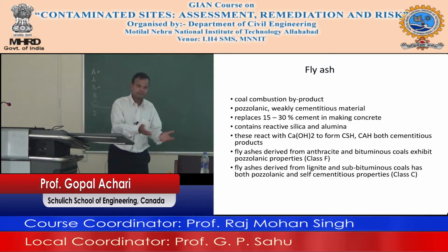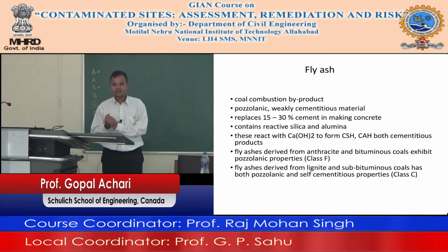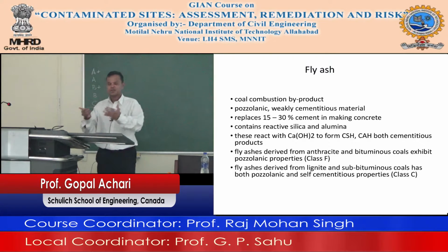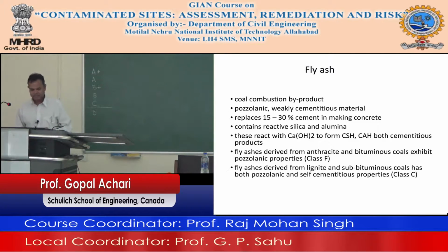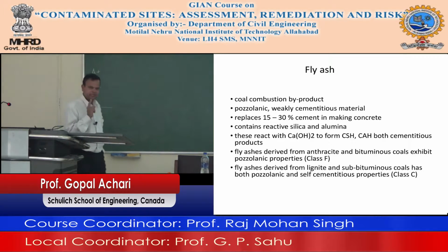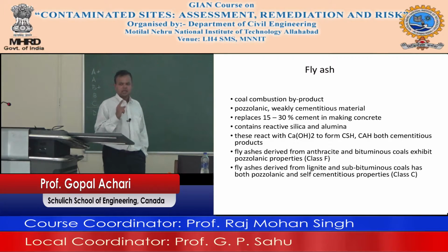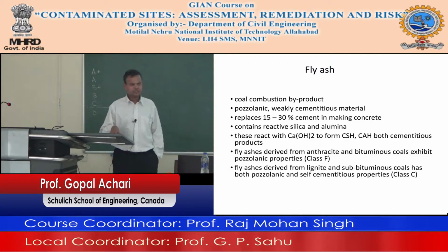Otherwise, you add a little bit of lime, and this reactive silica, reactive alumina will start to have similar reactions and form calcium silicate hydrate and calcium aluminate hydrate. Okay, so the reason I am spending time with fly ash is I know we have a lot of fly ash here as a waste. You also have a lot of waste here. Maybe the two can go together.